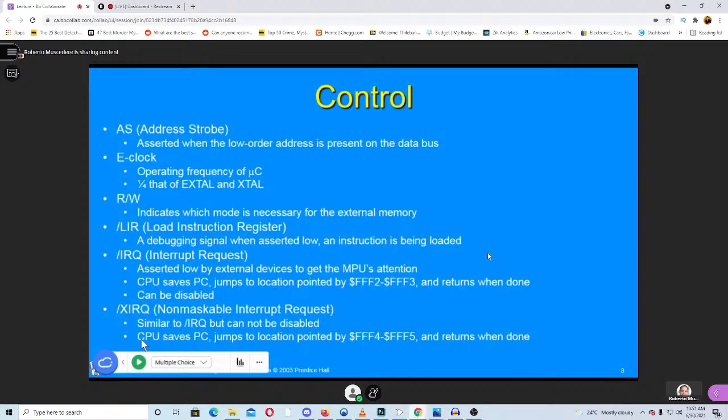Because if you stopped a hard disk in the middle of a write to a sector, that sector is going to be bad. Something's going to be wrong with it. The sectors have to be written completely, just like flash memory would. If you don't write it completely, the process has been interrupted, it's not completed, and some of the bits won't match up. There's CRC bits and all these types of things that make sure your data is correct. If that stuff isn't written correctly, then the sector is considered bad. And we certainly don't want that.